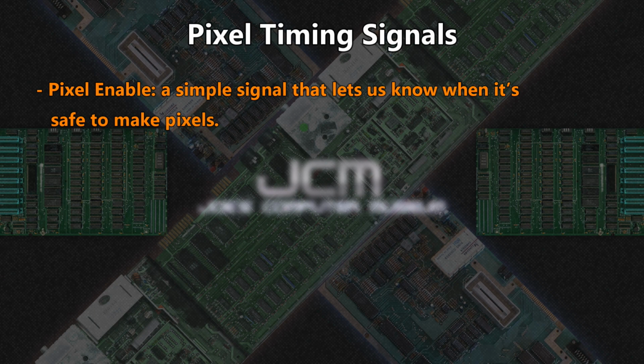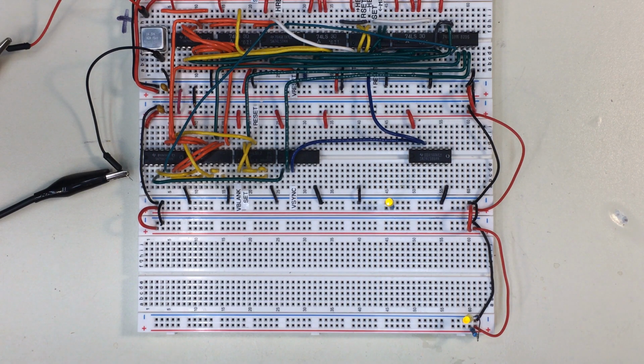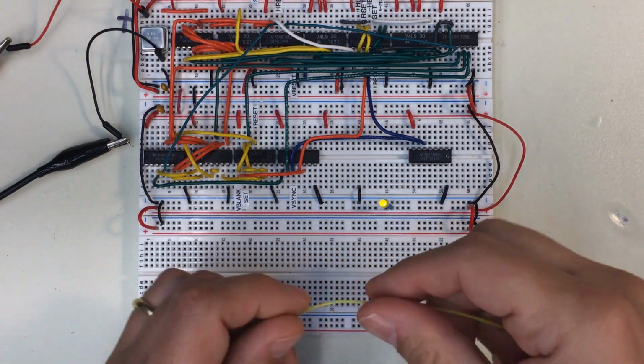The first signal we need is the Pixel Enable signal. This signal is used later as a chip enable reference. It helps us ensure that active video output is generated only during visible lines, and then only when horizontal timing isn't happening. It's generated by pulling V-blank and H-blank into the 74LS32 OR I added before to give us not PixN. Let's build it. This one's easy. We bring in H-blank, and then V-blank. Let's show it on the scope.